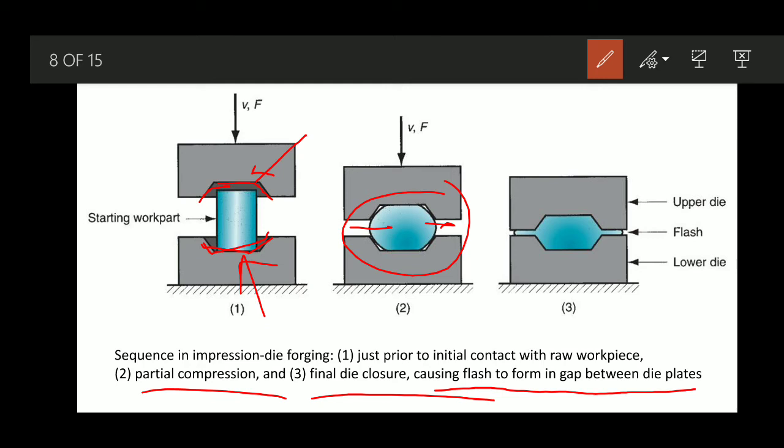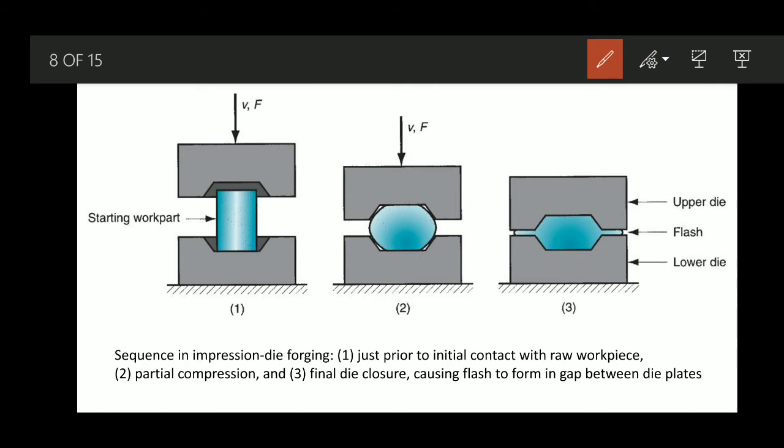between the die plates. So basically what is happening is that we have provided some extra material, the initial stock material. Because of that, we can be sure that it will flow through all those nooks and corners which are unfilled. Otherwise, if we provide just enough material, sometimes it may so happen that somewhere there may be little flow, some gaps, and it may not fill up properly.